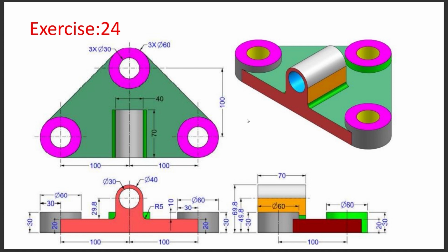From these different views, it is evident that it will be better to start from the top view, and we'll make half of that one and that to be mirrored with respect to the central axis. And after sketching this one, we need to extrude this one to 2 different depths, because you can see here this location and the central location we are having different depths, right? And after finishing this one, we need to start from the front view. Okay, so without wasting time, let us start our modeling using Autodesk Fusion 360.